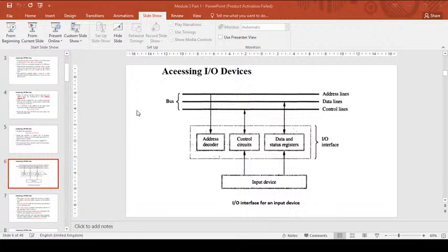So these are data in, data out, status and control registers. Here you already know the use of data in and data out. And then in the status register, which is an 8-bit register, you have S in and S out. You know that S in and S out are status control flag registers, right?